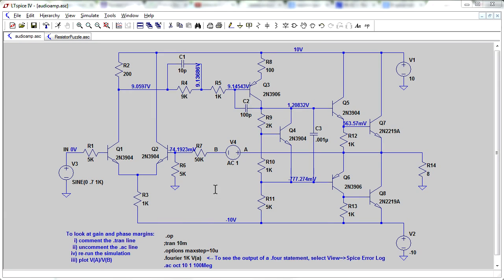And so many tutorials out there just completely skip that first basic step. They go straight into transient analysis, because it has the eye candy, it allows you to probe waveforms and see your oscilloscope-like waveforms around your circuit. But really, that is a more advanced analysis feature than your basic DC operating point stuff. So this is very important to know, as a first step to your Spice analysis. Yes, it's not very sexy, but it's vital to know.